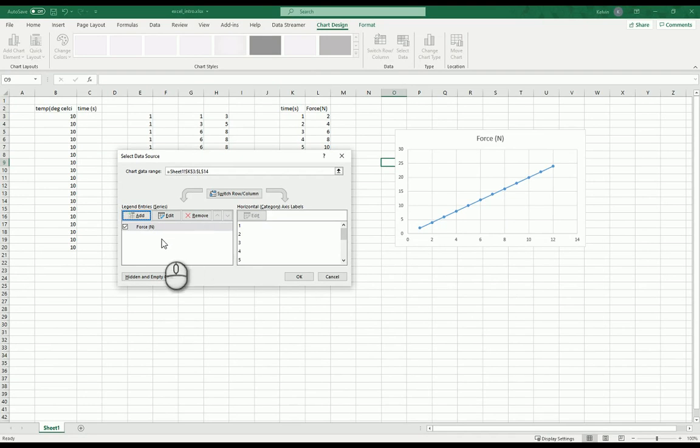So there we have it. We have our first plot of time versus force. As I go forward with the next example with the shear force and bending moment diagram, we would see how we could add a title. We could add x-axis title, y-axis title, and we could actually do two plots on one graph. So what we will do is plot the shear force and bending moment diagram on one plot, just to make things a little simpler.